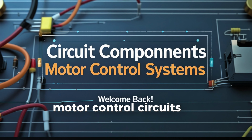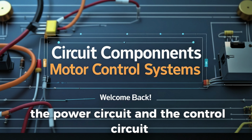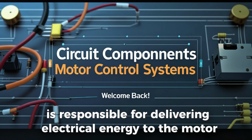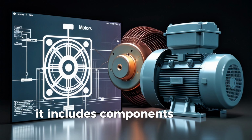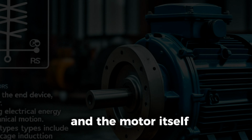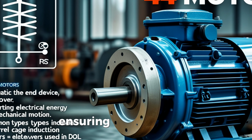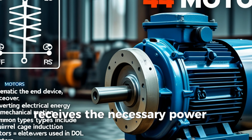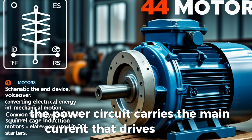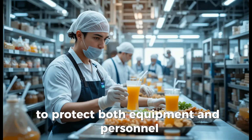Motor control circuits are generally divided into two main parts, the power circuit and the control circuit. The power circuit is responsible for delivering electrical energy to the motor. It includes components such as circuit breakers, contactors, overload relays, and the motor itself. These components are designed to handle high voltage and current, ensuring that the motor receives the necessary power to operate efficiently. The power circuit carries the main current that drives the motor and is built with safety in mind to protect both equipment and personnel.